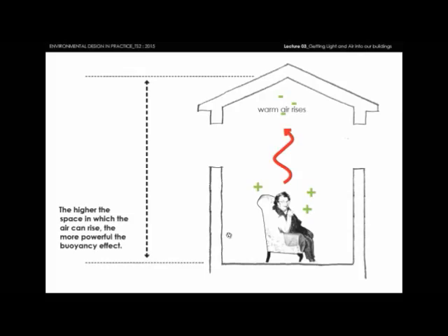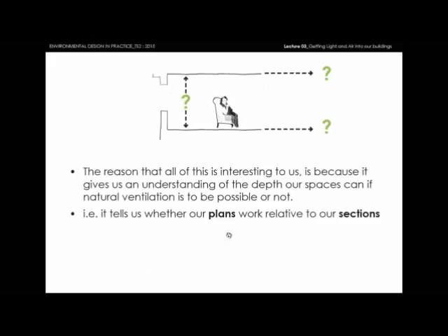The reason that relationship exists is because, of course, the higher a room is, the more potential there is for buoyancy effect. Buoyancy effect, very simply, is the effect of warm air rising above your head. When it rises, it draws cooler air in to take its place. You end up with this natural circulation of air from a low level to a high level, and that's a force which can drive natural ventilation.